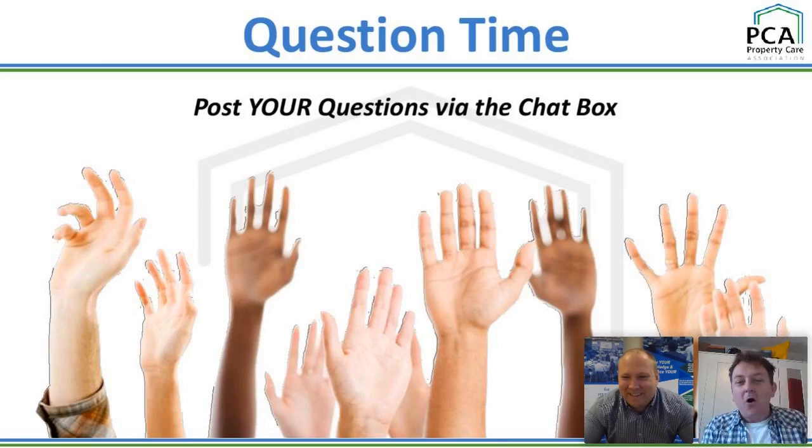Well, anyway, on to questions. Now, they've got one on fire doors. I've just seen that one, so let me answer it fairly quickly. Obviously that 10 mil gap doesn't apply to fire doors, and you'd have to comply with your own building regs, which is obviously Part B. But yeah, exclude fire doors. If you're looking at your typical domestic dwelling, where you're looking at your bedroom settings and all of that, then you're going to be looking at your standard stuff there.